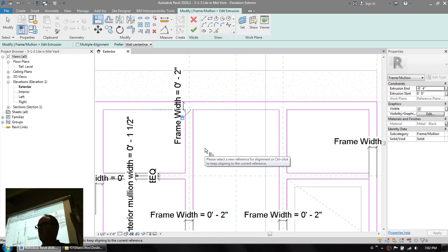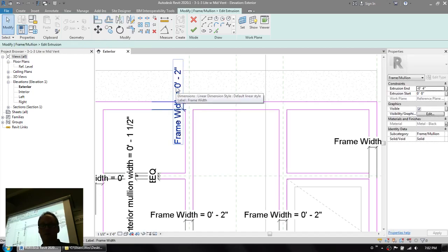So by locking these 2 sketch lines, by constraining them to this one on the left that has a dimension on it, I know for sure that when this parameter changes its value to say 3 inches or 1.5 inches or what have you, all of these 3 lines are going to move together at once. So that's a constraint. Anytime you lock and align things together, that's a constraint. So there's different kinds of constraints. This is an edge constraint.